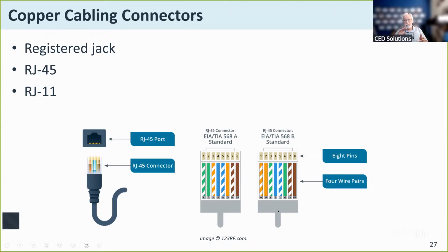And you'll notice what it does. I was talking about the transmit and receive pins. It crosses those over, and it simulates a modem in the middle of that connection so that it's transmit, receive, transmit, receive. So it's called a crossover cable.